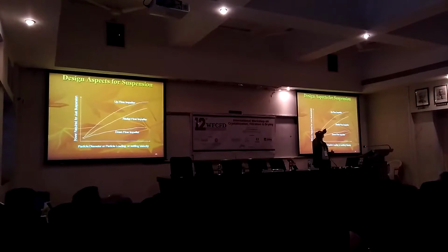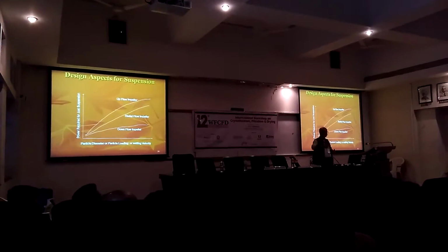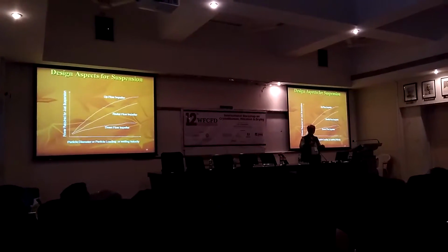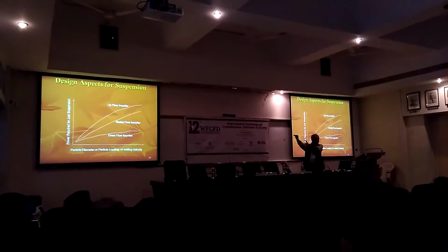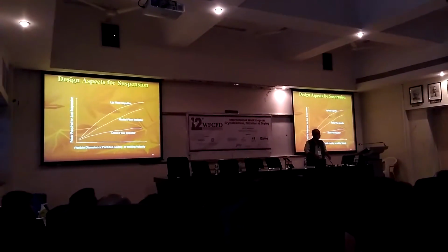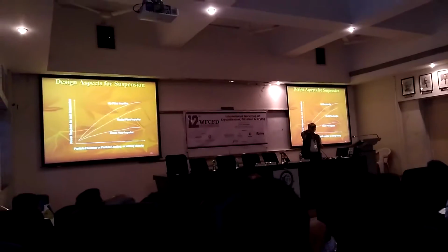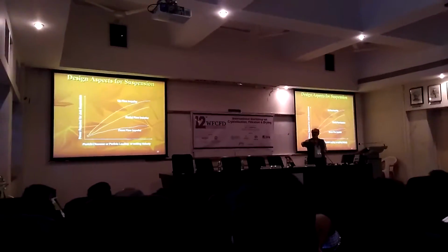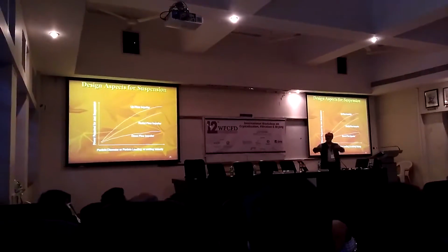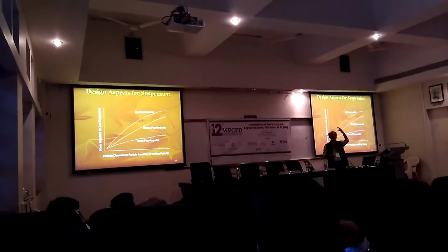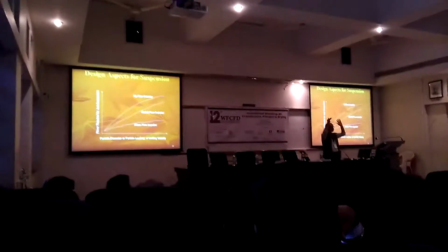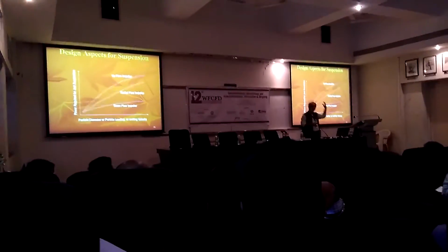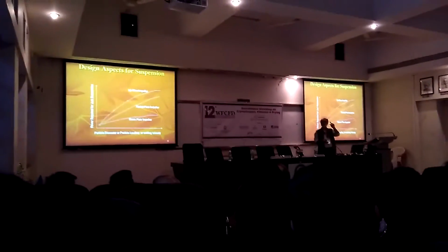So it's like this, I have got a fan out here. Right? I am sitting out here. If I have a fan directed towards the wall rather than directly impinging on me, by the time the air coming from the fan changes its direction, half of its velocity head is lost. So I need to operate that fan at a much higher speed as compared to the fan which is located just on top of my head, which I can operate at a much lower speed.